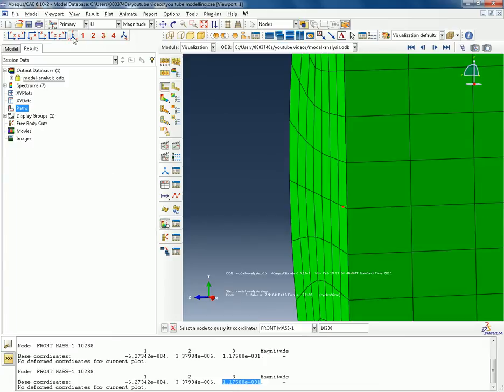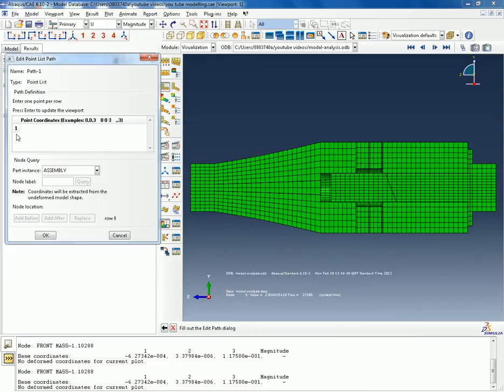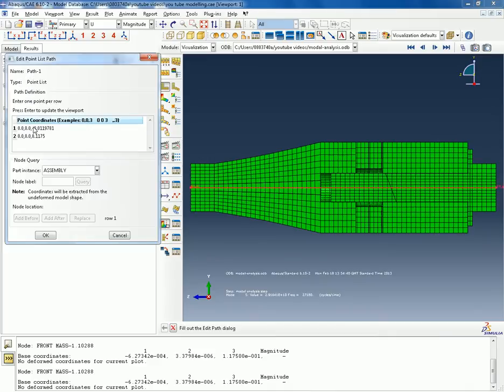Within the path, I'm going to select this, the first path. We only have this path. I'm going to select MD4 to get the real length of the transducer, and I'm going to select include intersection, where the calculation will consider each node or each element node value that the path passes through. The x value will be the true distance around the transducer. For the y value, I'm going to select the mode I'm tracing, which is the longitudinal mode, and I'm going to draw the response in the z direction, the longitudinal response, which is represented by 3.